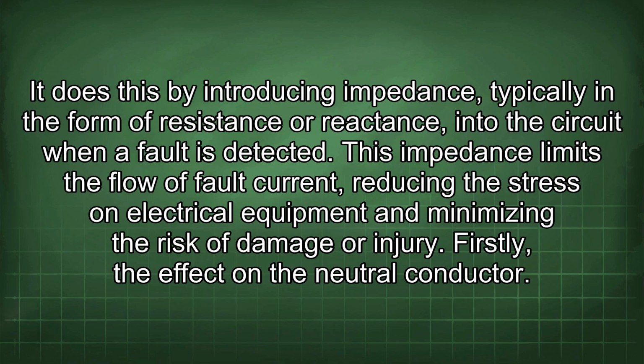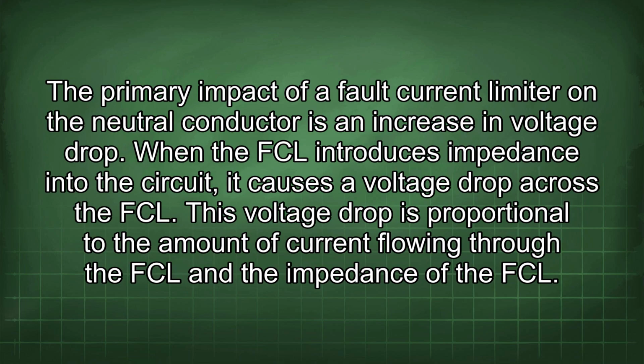This impedance limits the flow of fault current, reducing the stress on electrical equipment and minimizing the risk of damage or injury. Firstly, the effect on the neutral conductor. The primary impact of a fault current limiter on the neutral conductor is an increase in voltage drop.